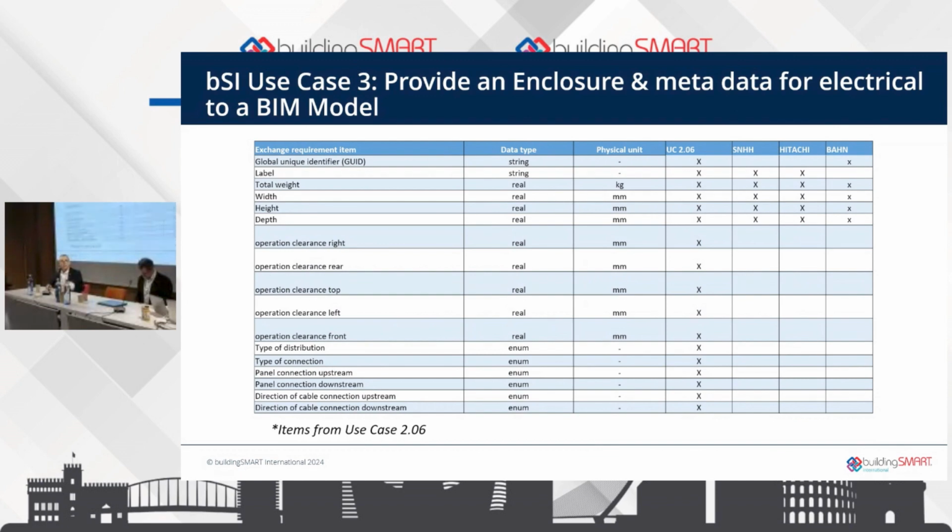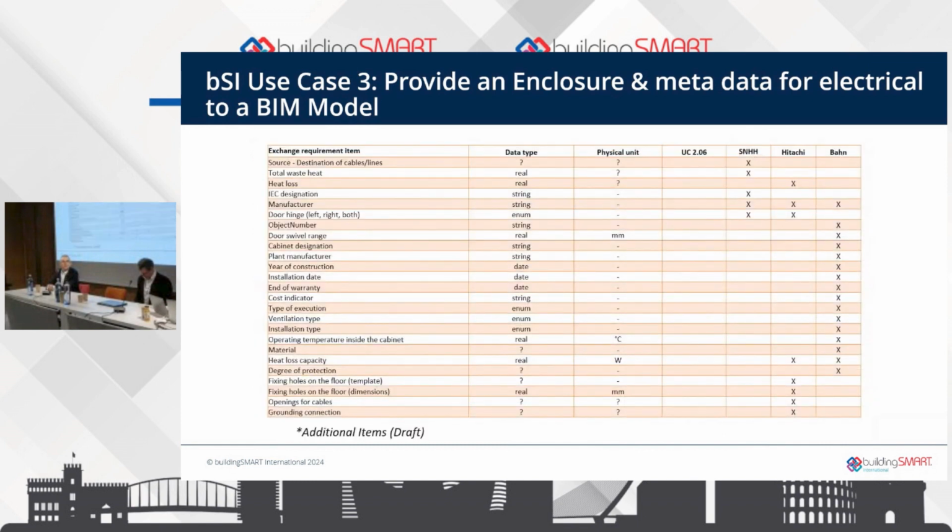So we need to go through listing the properties for the level of information or level of geometry that we need, and making sure that we can find these properties in the IFC property set, and if not, somewhere else. The somewhere else will be in the bSDD, coming from other classifications, or as a user-defined property set. So this is what we are doing, mapping this.